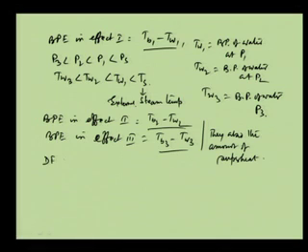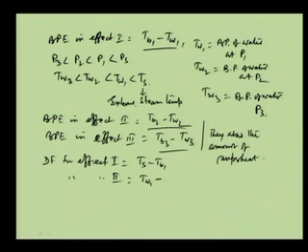And so, the driving force for effect 1 will be equal to Ts, the steam temperature, minus Tb1, the boiling point temperature. The driving force for effect 2 will be equal to Tw1 minus Tb2, and for effect 3 it will be equal to Tw2 minus Tb3.